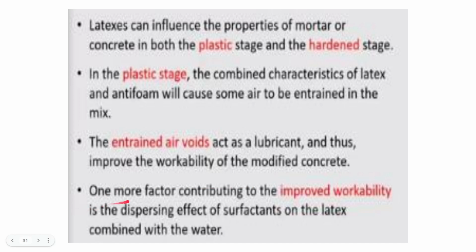One more factor contributing to the improved workability is the dispersing effect of surfactants on the latex combined with the water. So these are the main factors which are improving the workability. One is entrained air voids, and second is the dispersing effect of surfactants on the latex, which is combined with water.